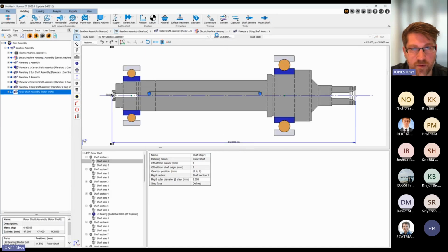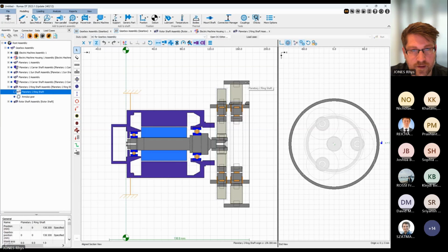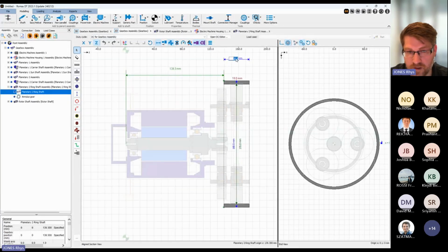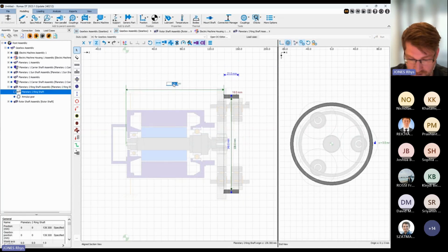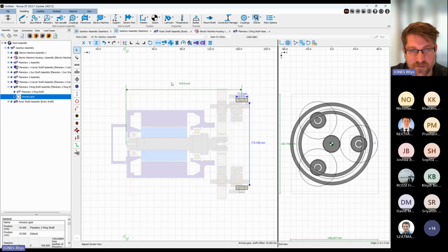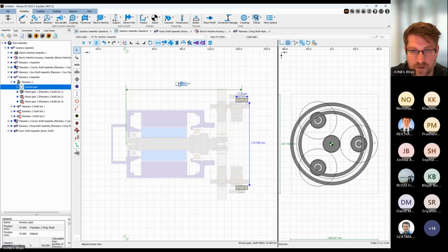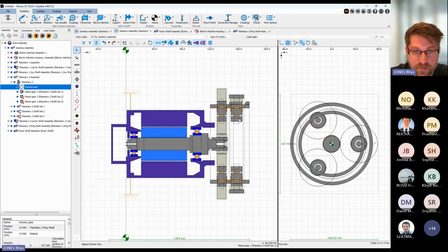There, we will open up here. And this one now, we want a face width of 21, a bore diameter of 130, a pitch diameter of 140, and an offset of 146.8, which again will move this into the wrong position. There we go. So that now creates our planetary system for 2 of them.